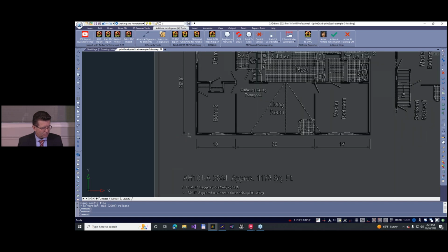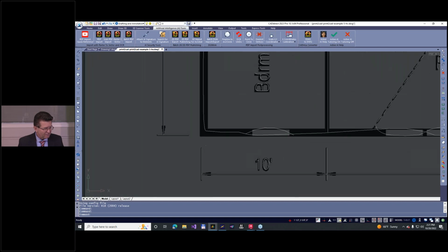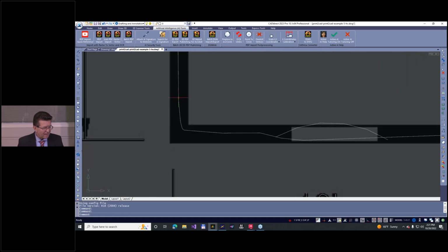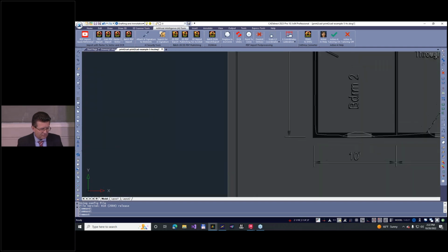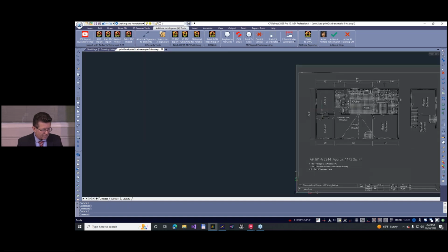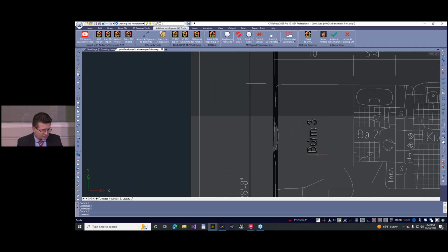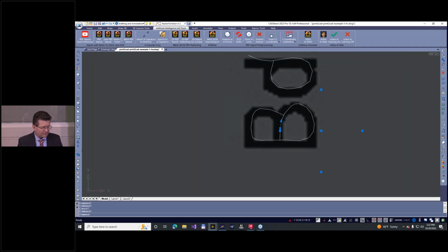And look, what you see here is a perfect raster to vector, because the vectorization is center line tracing, like an algorithm that traces the line in the center of the pixel traces and tries to make curves. Look here, this 10, you can see this is a line, nothing more, a simple line. You can see these are lines too. So this is a perfect center line tracing, but it's not text.